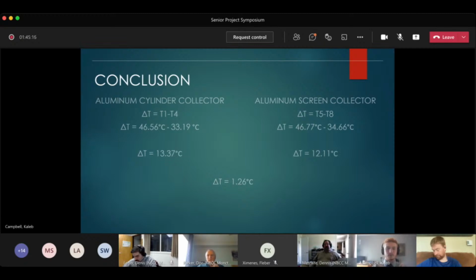No. Okay, well, that's unfortunate, because I think true that you can show these as temperature, and if we assume that for all things being the same, that's where we can say that. If the mass of the air flowing in both of your collectors are the same, and we measure that by the amount of air for a given amount of time going through them, that's why you had to make sure that the air flows were the same, right? Yep. And we assume that the specific heat of the medium is again the same, so air for both, right? So if those are all fixed and constant, then we can make the direct correlation that an increase in delta T will be proportional to the increase in energy, right?